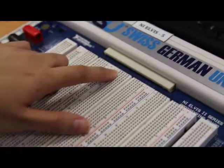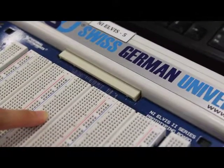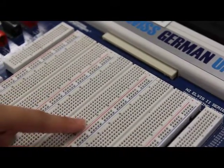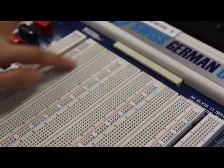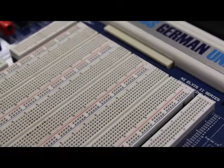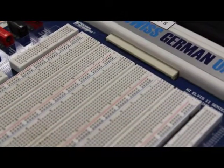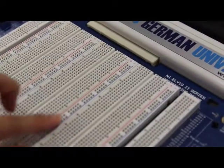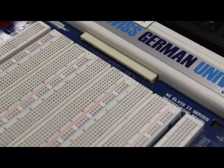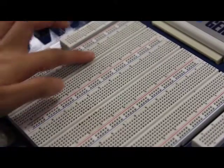There are alphabets, this A, B, C, D, E. It means that all of these holes are connected horizontally, but this group and this group are not connected horizontally because they are separated by this spine. And these holes, this one and this one, are connected vertically, and it's not connected with this.